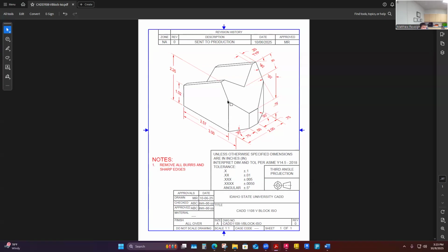And then it's going to turn this way and it's going to look in my front view, because my eyeballs are here and this surface is perpendicular to me. This is going to be a true length. These are going to be true lengths. So if I can define them by some view, by kind of working top, front initially, can I figure out where that point is? Maybe. And so if I can define that, it's going to be a true length in my front view. So will this long line across here.